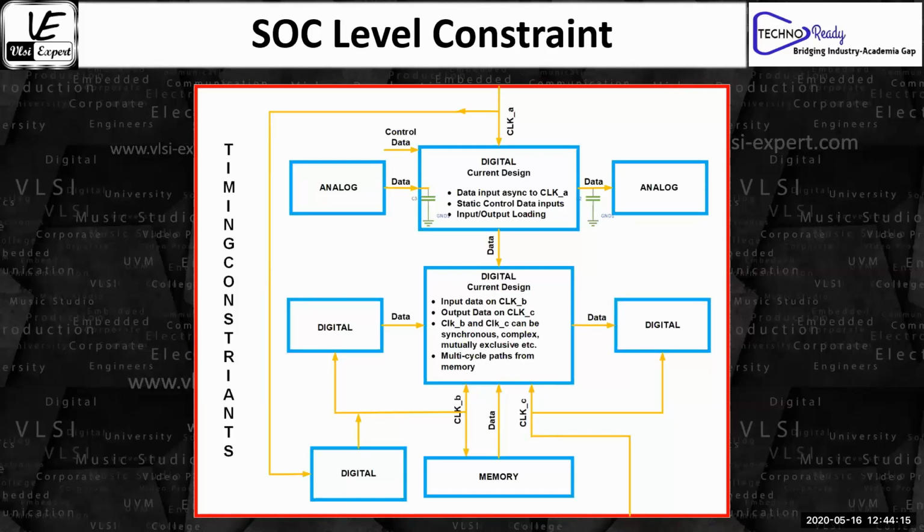I have one question. I just want to understand the differentiation between when we call a design a synchronous design and a design an asynchronous design. By virtue of what are they classified as asynchronous or synchronous? And when we have to define constraints, in my constraints I see many data checks defined at the CDC crossings, so we set a false path or a multi-cycle path on them. With respect to the clocks and the design itself, I just want to understand what the jargon means in the first place.